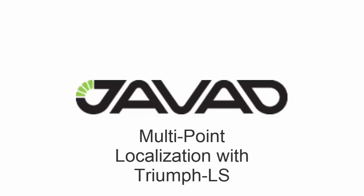Today we're going to be talking about multi-point localizations with the Javad Triumph-LS. Conformal projections, whether that be state plane or UTM or some custom low distortion projection, are typically the easiest way to work with GNSS-derived geodetic positions in land surveying.